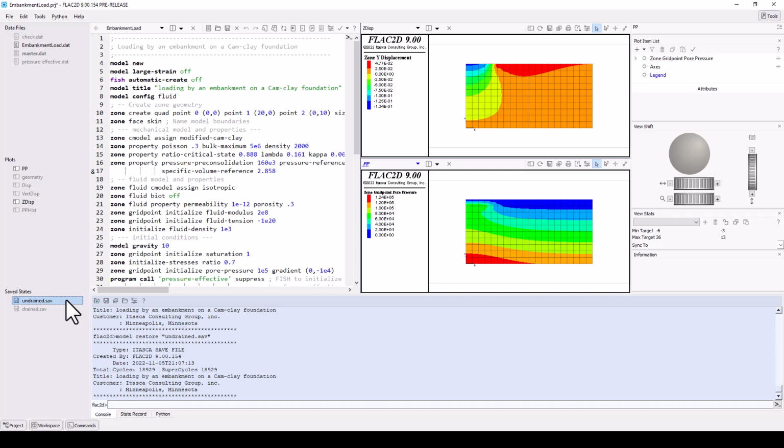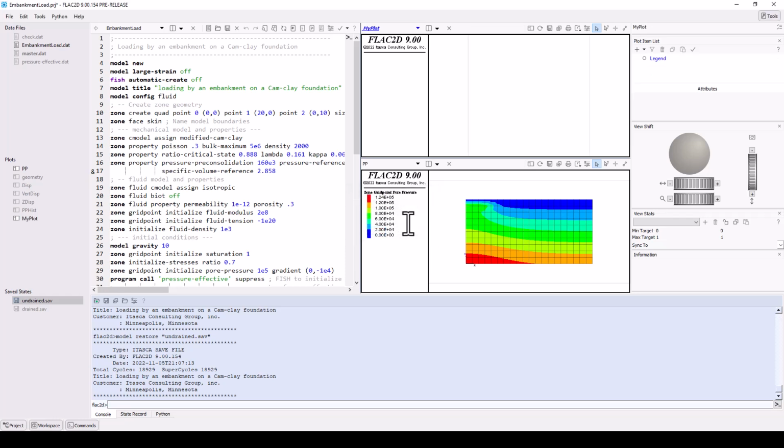To capture important model creation steps, represent actual construction stages, or, in parallel, to explore different material properties, conditions, or engineering designs. To make a new model plot, click the Content Selector menu in the Z Displacements plot tile. Select New, and then Plot. Name the plot, My Plot. The tile now displays an empty plot. Note that the previous plot still exists.